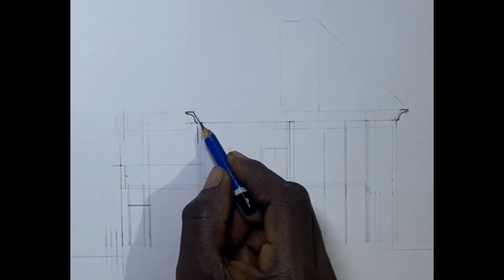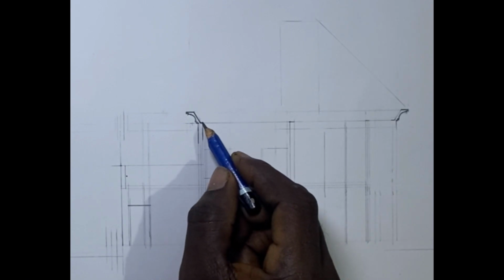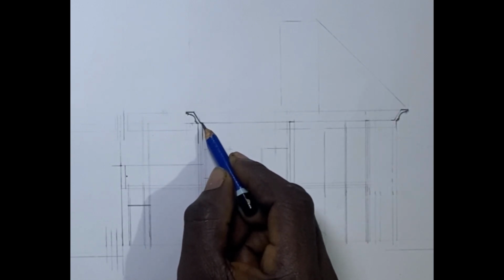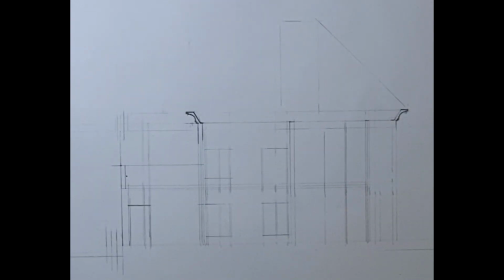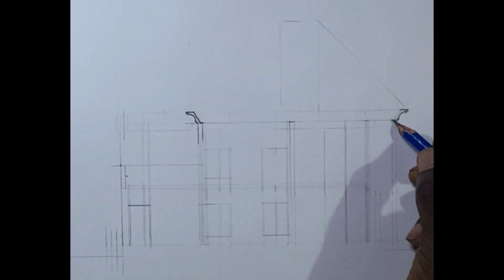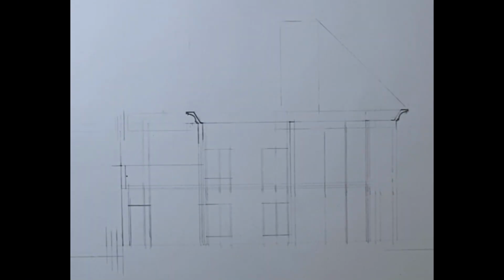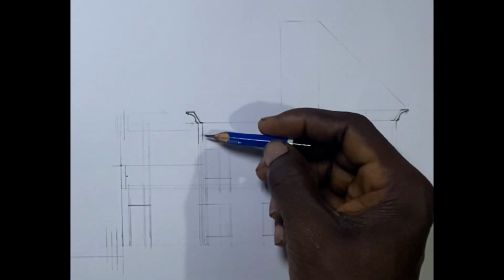While from where we have the fascia concrete stopping to the end of this wall here is equivalent to 75, since 150 plus 75 is equivalent to 225. So same thing at this edge here. So we now have a concrete fascia of 150 millimeter thick flushing into our wall.